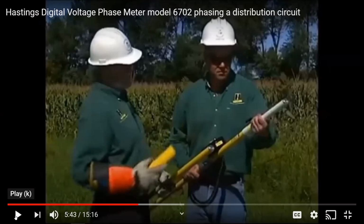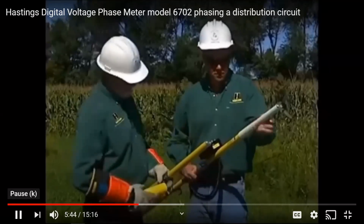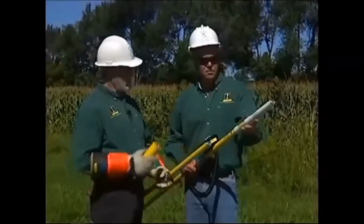So now we're not testing anymore for presence of voltage. We're actually introducing a voltage onto the conductor with that white section. All it is is a huge resistor, and we're introducing a DC voltage with what they call a high pot adapter. So a good question would be, what additional piece to the phasing sticks is required for high potting underground cable? A high pot adapter. There you go. It's important that we put the DC high pot adapter on the metered end.